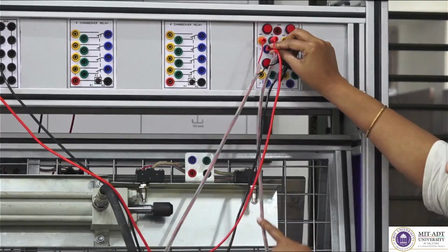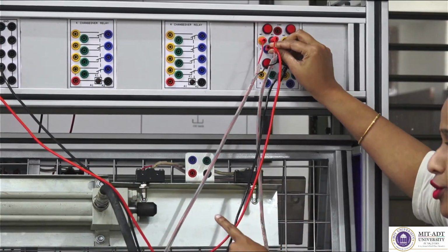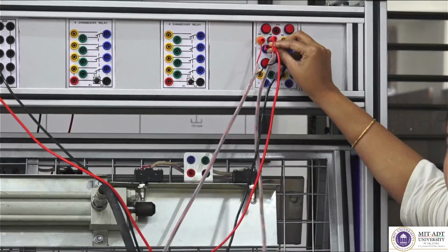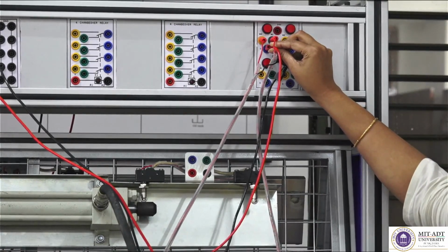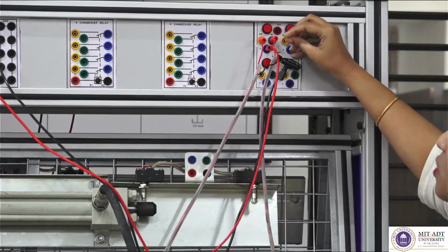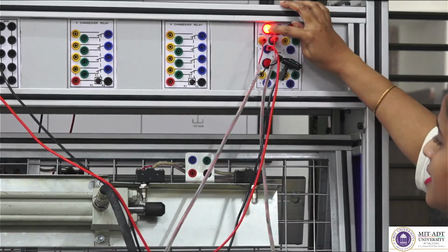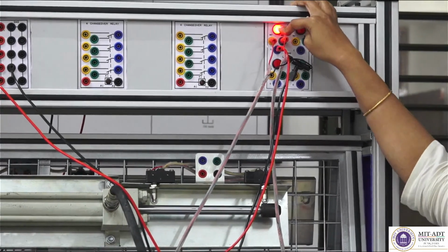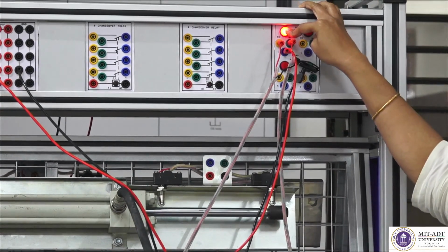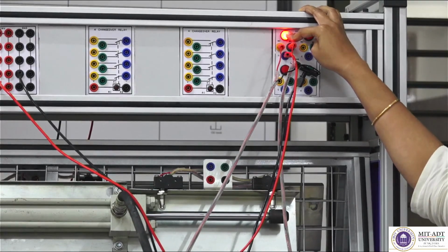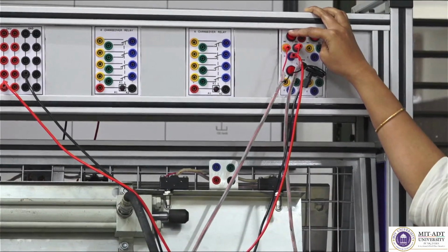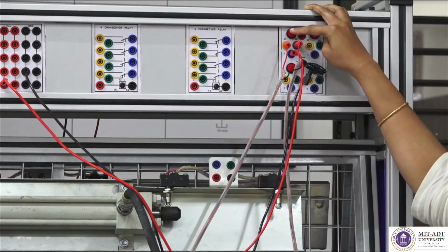So here you can see that the retraction motion of your double acting cylinder has taken place due to this solenoid which has been energized. So let us quickly press this latchable push button. So what has happened? Because of this non-latchable push button, I can continuously switch over both the solenoids. So here I can get better control.